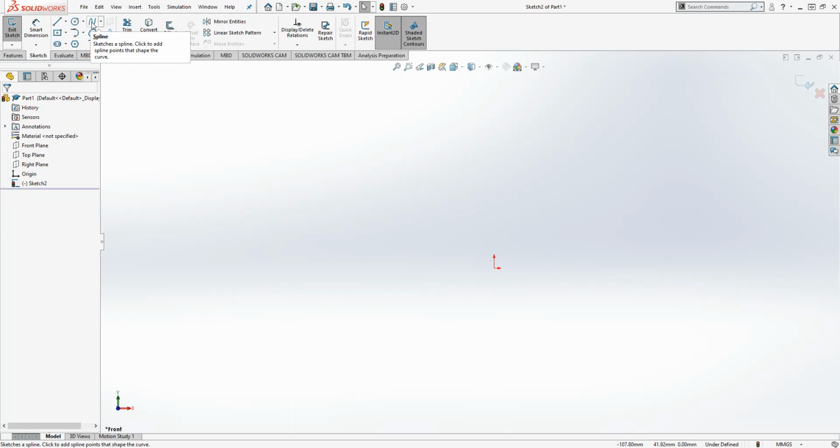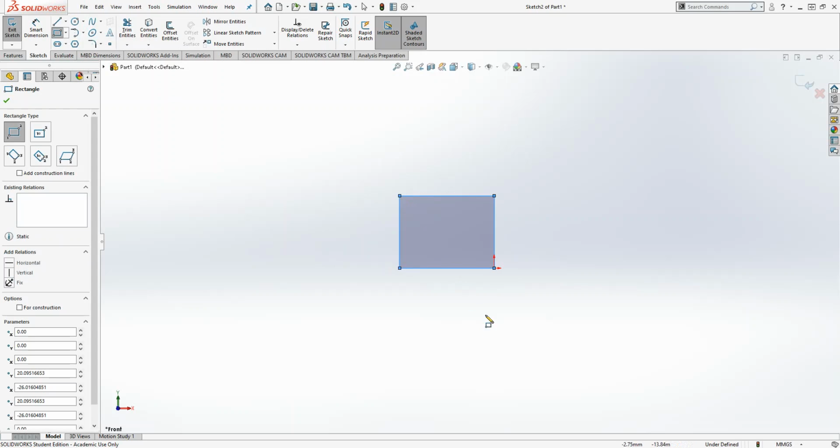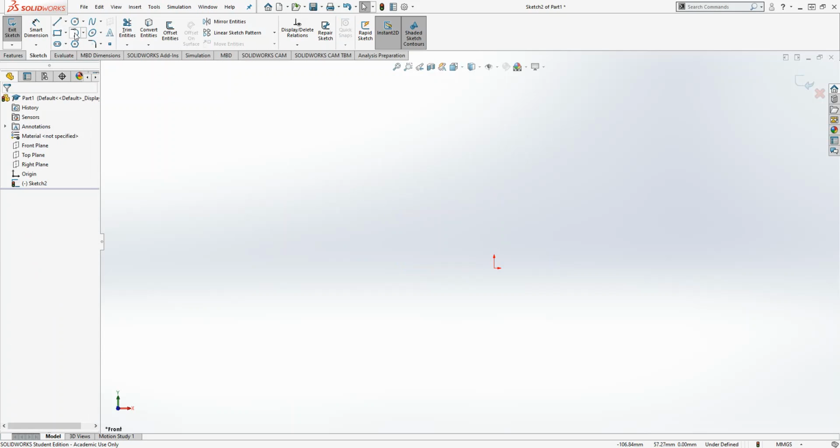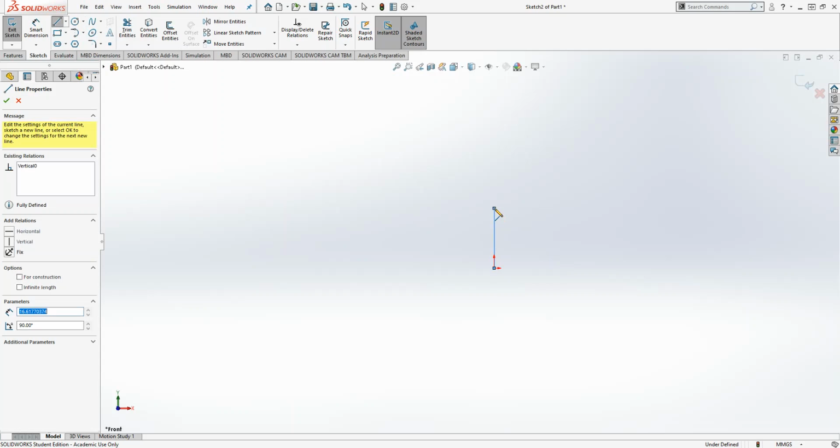You also have things like splines, where if I click it, it creates this curve based upon whatever points you have. So if you wanted to make these interesting looking oval-like shapes, kind of like an egg, splines are just ways of creating your own curves that are not super precise, but just something to use in general. And you can also see there are always drop-down menus, like spline, style spline, equation-driven curve. Lots of really unique tools, but all things I'd recommend you try out yourself.